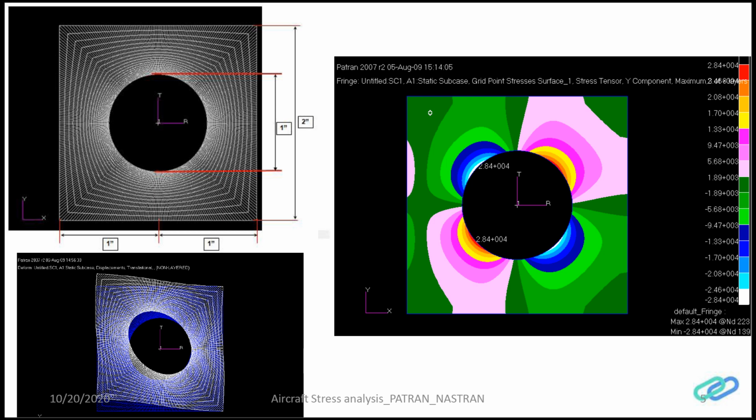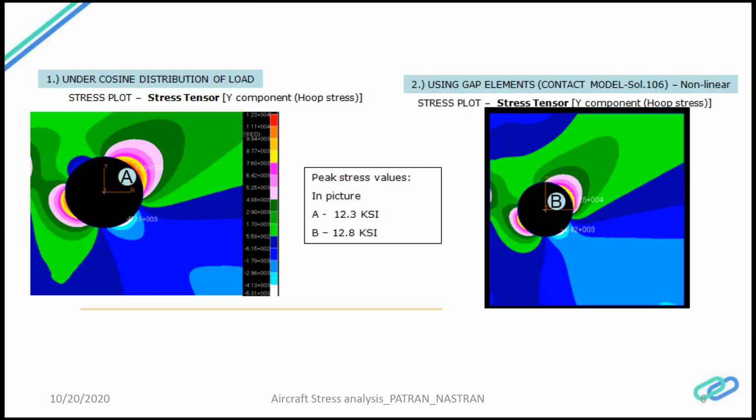You can see this typical example shown here for a 2 by 2 inch plate with a 1 inch hole diameter, and you can see the peak stress distribution around the hole. When I calculate the Kt, the stress concentration factor for a circular hole, which is 3 times the sigma, it is exactly matching the Peterson stress concentration factor. There is a book that gives the theoretical value.